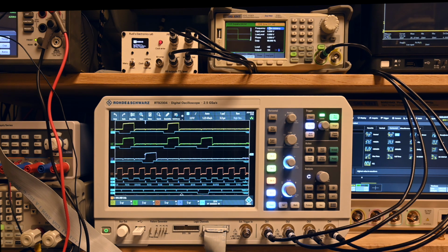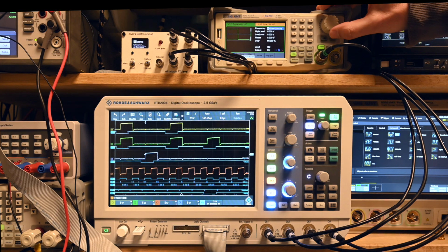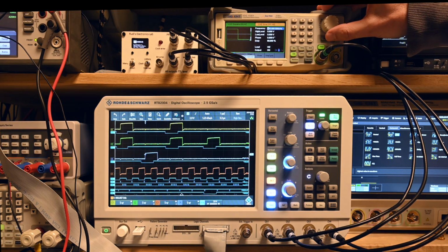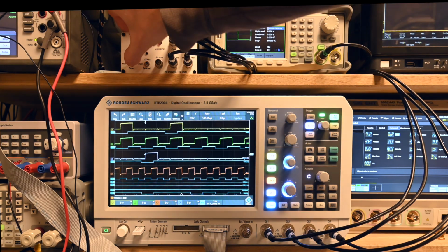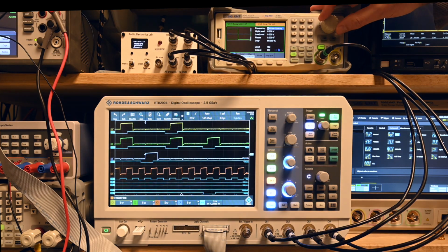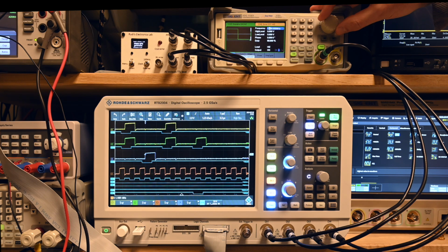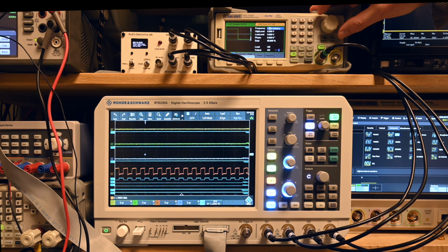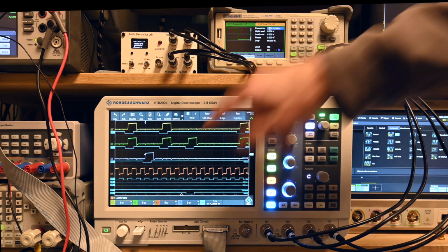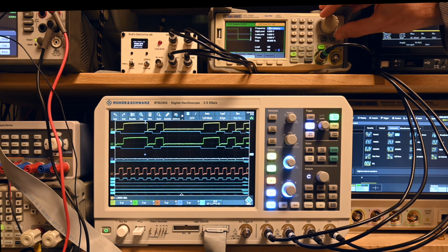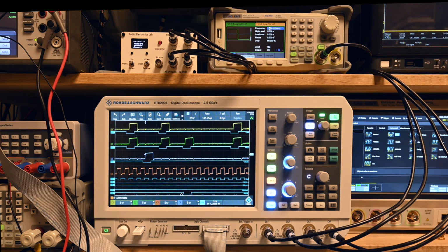So this debug interface can be used to investigate a little bit better to what speed the device can run. Now in the debug mode, as you can see, we can go to 900 kilohertz maximum. However, if we stay in a regular state, we can actually go faster. 1.2, 1.3 megahertz is still running well without the indicator going on. Everything is still fine. And at 1.4 megahertz it is not working.